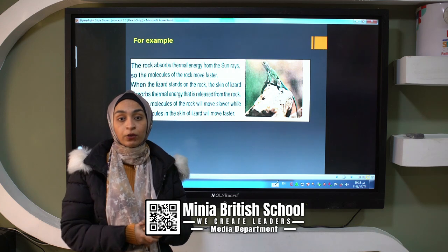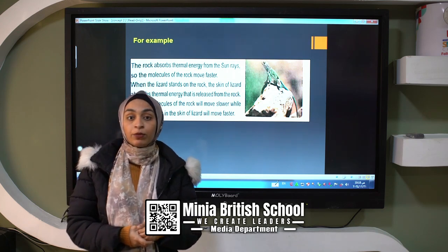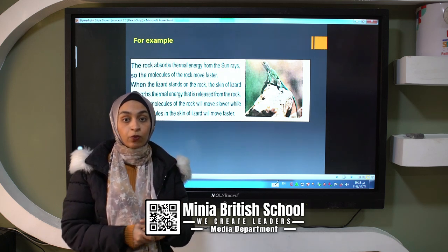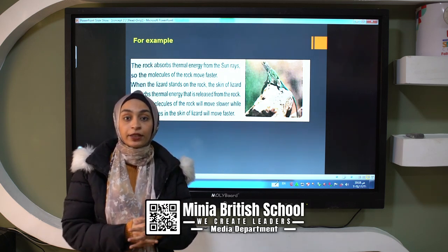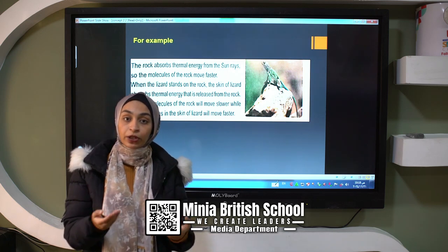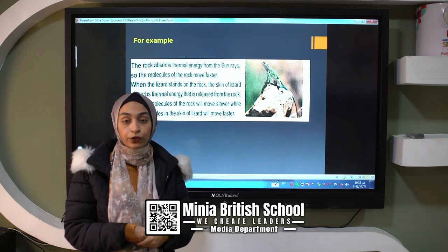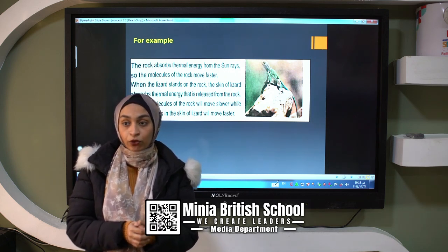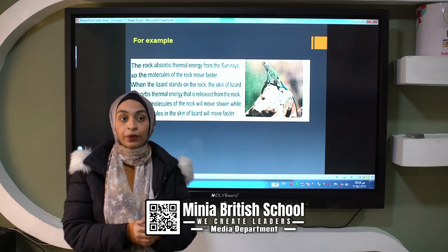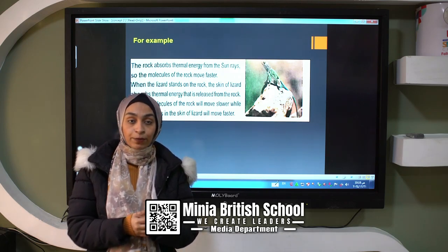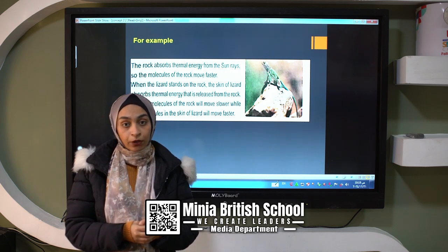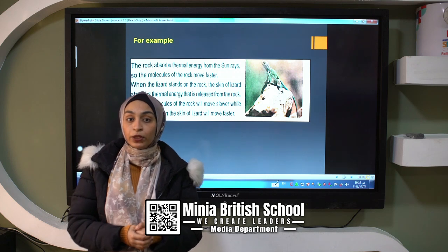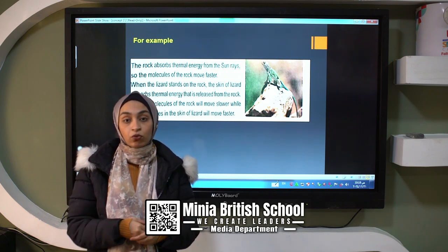Also the last material is glass. Glass is made up of limestone, soda ash and sand. We can mix them together and expose them to a high temperature in a hot furnace, so we can get the glass in a liquid or even molten state. And we can use a process called glass blowing to make different shapes of glassware, and finally leave it to cool, and we can use it as we want.